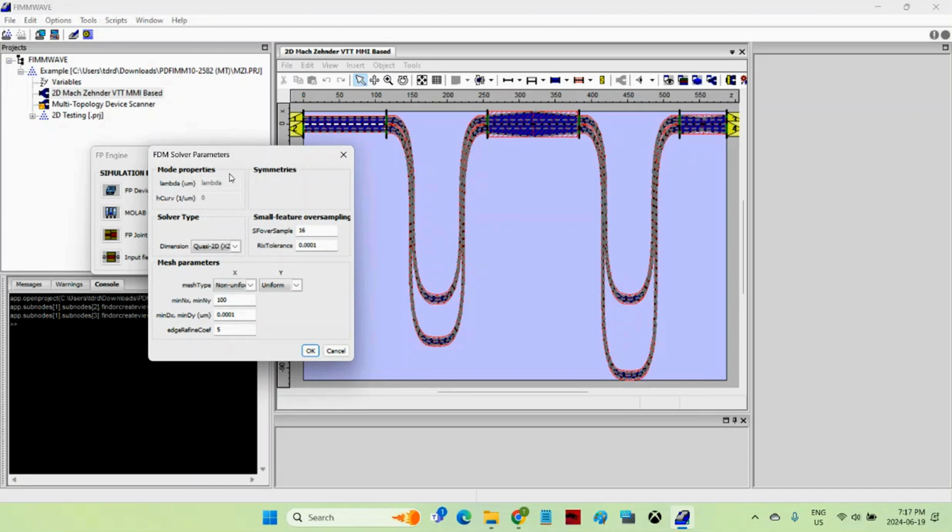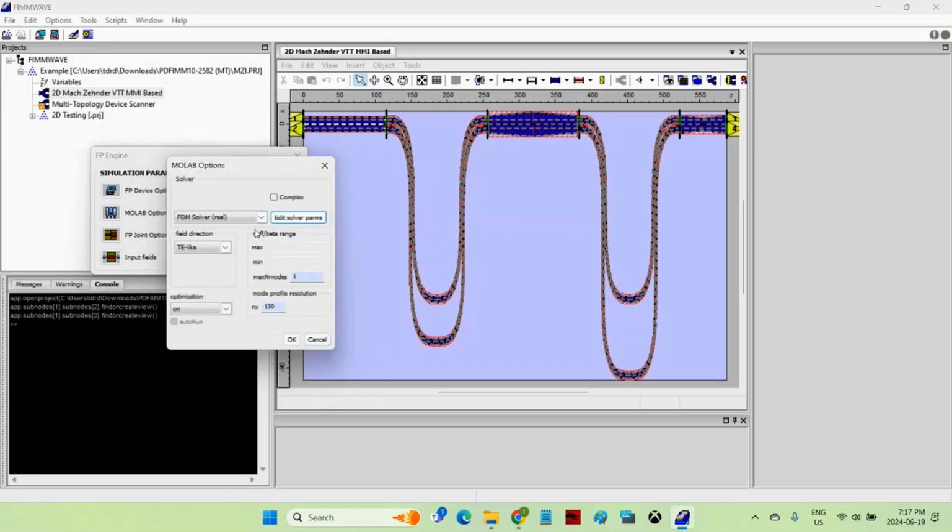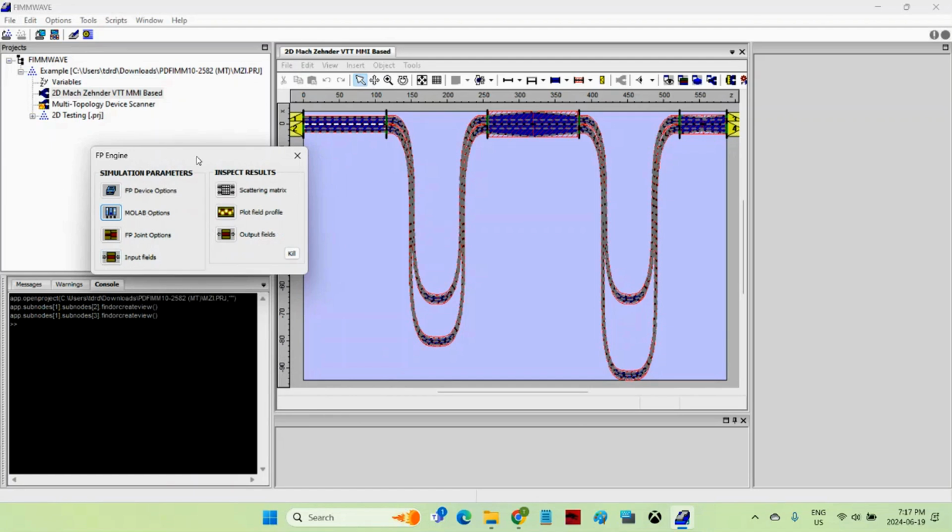This is a frequency domain solver, and I'm using a variable which I've defined in a variables node for lambda. In this particular case, the wavelength is 1.5524 microns. So once we've set all that, we can click the scattering matrix button, and the calculation is proceeding. The progress bar on the bottom left gives you an indication of how long there is to go. So it's going to take a few seconds, maybe in total 20, 30 seconds to calculate this large long arm Mach-Zehnder.